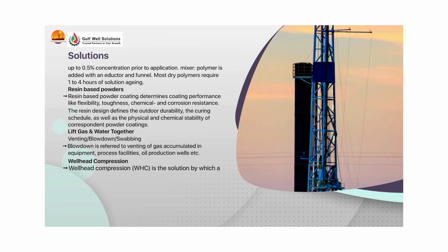Wellhead compression. Wellhead compression, WHC, is the solution by which a compressor acts locally over one or a number of wells. In this way, the back pressure for a number of selected wells can be reduced.